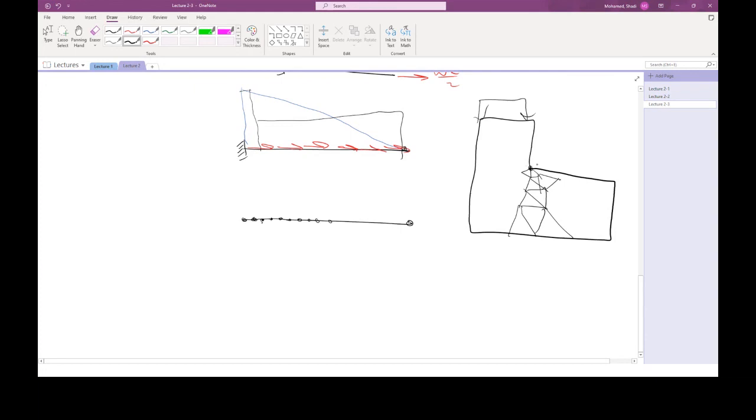So again, for example, when you have a stress concentration, such as when you have a reentrant corner, or if you have fracture mechanics at a crack tip, you have a stress singularity as well. So you need to have a very dense mesh right at the tip of the crack. So in these types of problems, you would know where exactly you have the stress concentration. So you populate this stress concentration with as many elements as you can. Get away from that, you can get away with larger elements. It doesn't really matter. But this will be a lot cheaper than solving this problem.